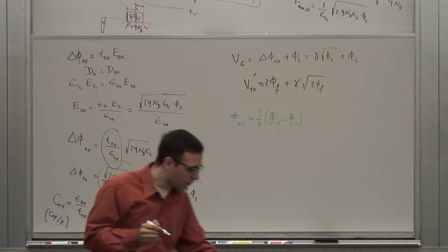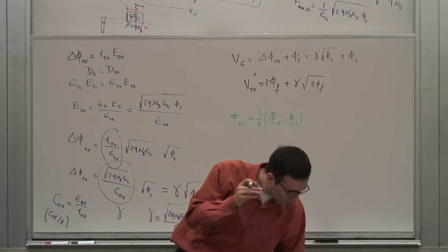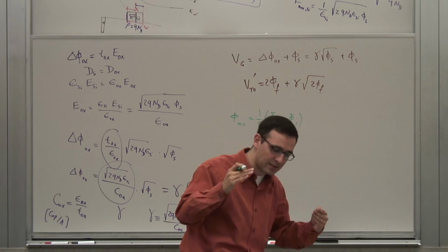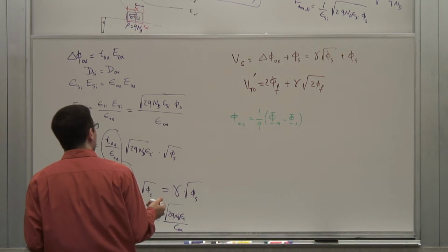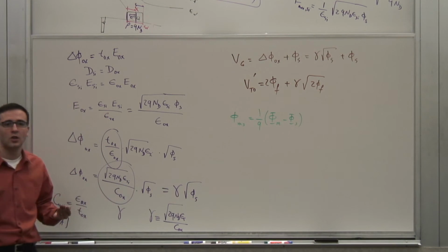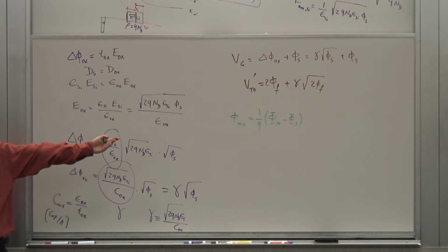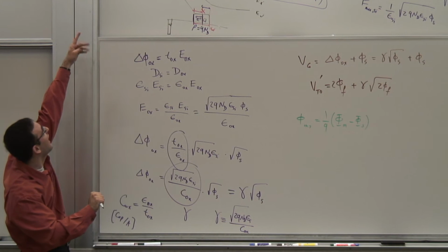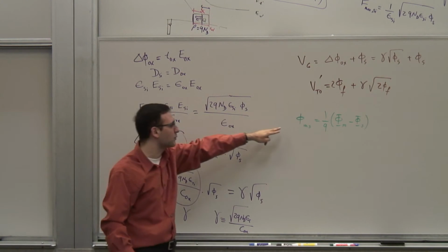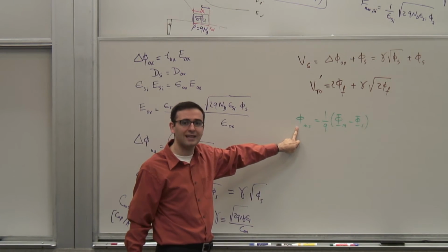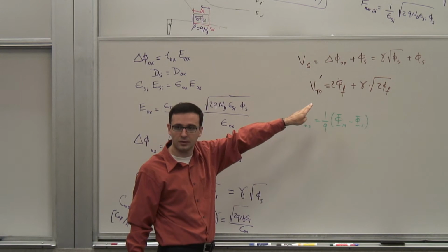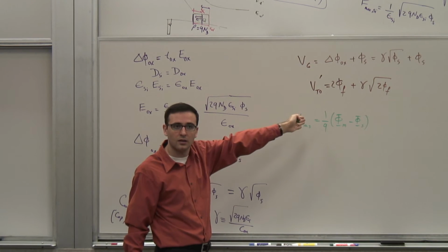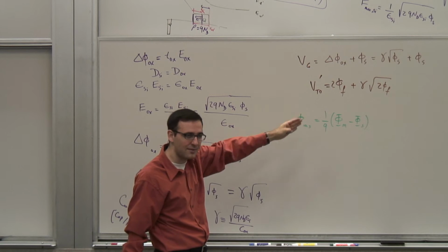If you apply this voltage to the gate, that brings you to the flat band condition. So this is the amount of extra voltage you need to apply to the gate to induce the flat band condition. So instead of the flat band condition happening at 0 gate voltage, it will happen at this voltage. So this will have to be added to my threshold voltage to give me the real threshold voltage to adjust for the difference in the work function of the metal and the semiconductor.